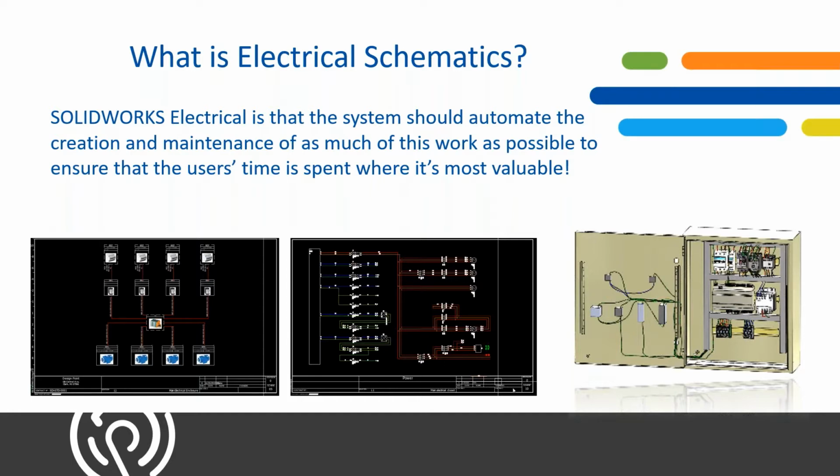After we're completely done with our 2D project, we open it up and convert it into a 3D assembly, okay? But a lot of your electrical schematics are used to plan out your project, to describe your project with electrical symbols, and also to completely do a whole electrical panel layout, whether it's a panel, a floor, or just a harness. Okay, so this is used to create and lower the maintenance of your changes, and it's supposed to give the user a lot more time to make changes and focus their time on other places in the project.